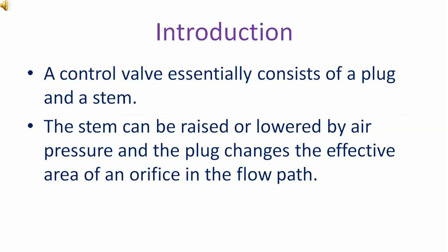A control valve essentially consists of a plug and a stem. The stem can be raised or lowered by air pressure, and the plug changes the effective area of an orifice in the flow path.